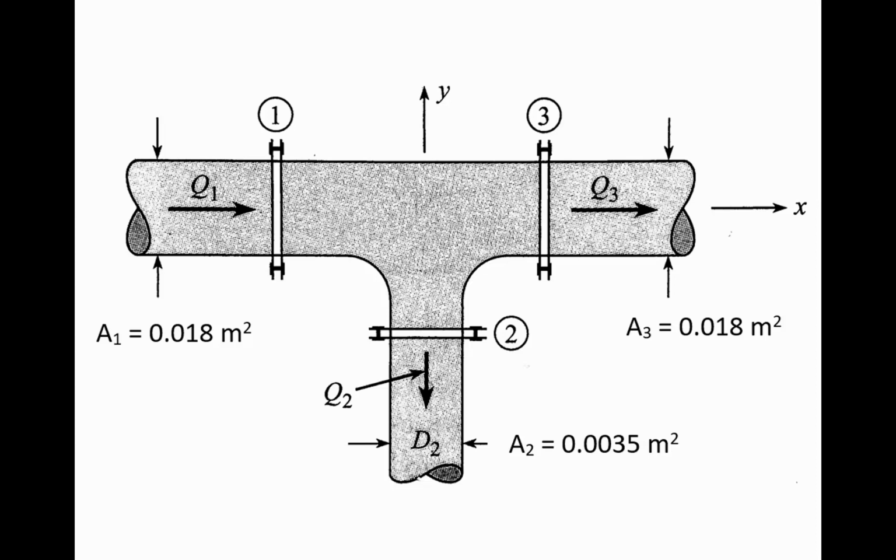Sometimes there are problems like this, where it's a union of 3 pipes coming in together. And so if 3 pipes are coming together, then you're drawing a control surface and you're cutting these pipes in multiple locations. This kind of curved shape just means that the pipe actually continues out of view, that it's not an actual physical cut or break in the pipe, but it's just we're drawing our control surfaces so that we can apply the momentum equation to what's going on inside of that control volume.